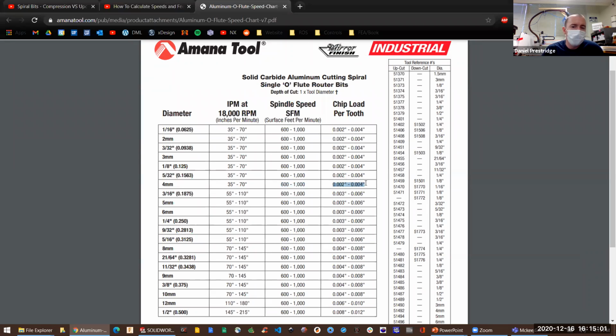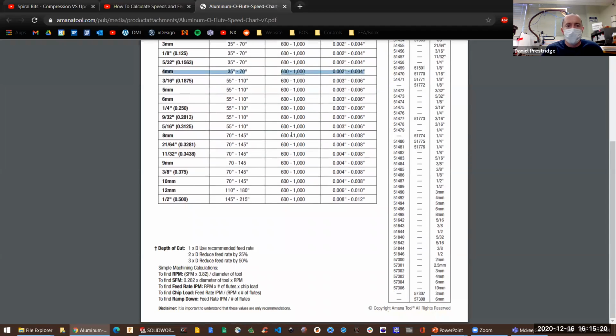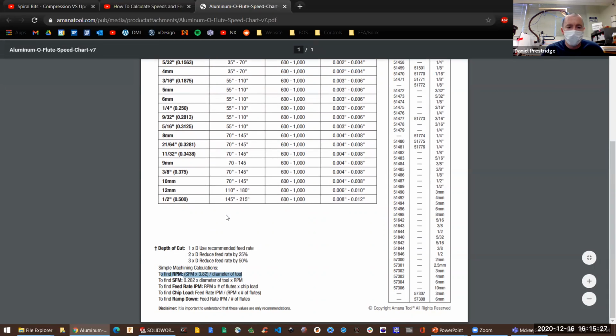I'm not going to really go into that too much either. I think that it's better if you watch the videos that are dedicated to it. But the combination of all of these guys, and then maybe dialing it back just a little bit, can really get you a good starting point for it, because it's the most efficient way to move through the material with their tool. And then they give you how to find RPM as that surface feet per minute times 3.82 divided by the diameter of the tool.